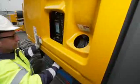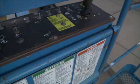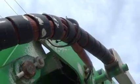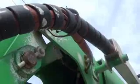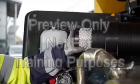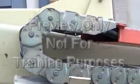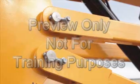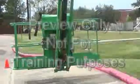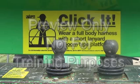communication systems. The following items are also required in the inspection: all ground-level controls and provisions for overriding of upper controls, all chain and cable mechanisms, paying attention to adjustment and worn or damaged parts, the lubrication of all moving parts, inspection of filter elements, hydraulic oil, engine oil, and coolant, visual inspection of structural components and other critical components, like fasteners, pins, shafts, and locking devices, instructions, warnings, and control markings, and safety devices.